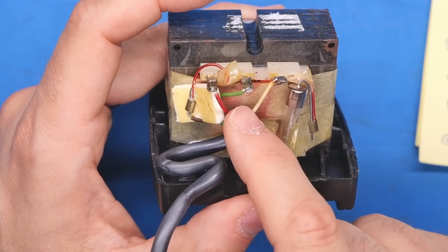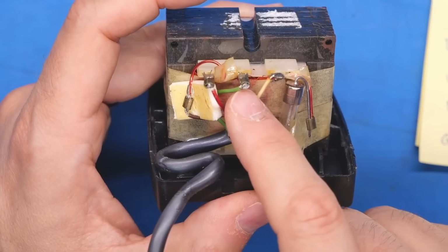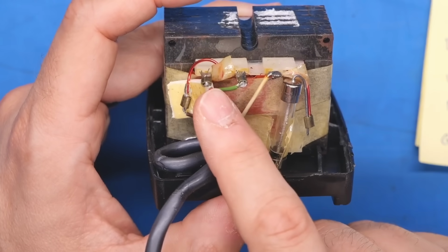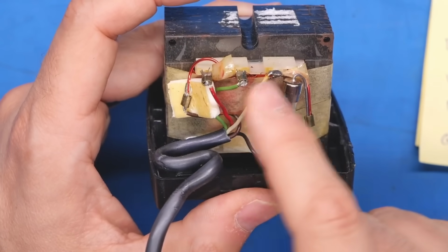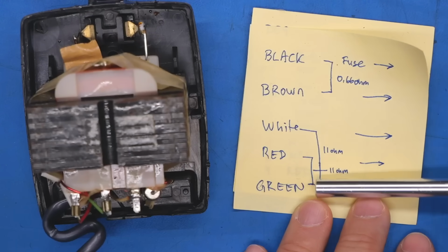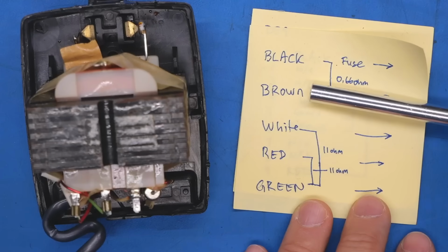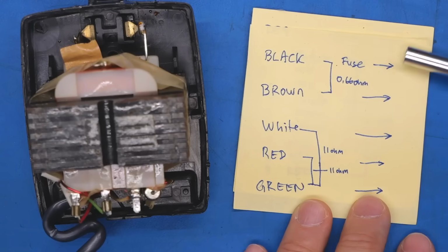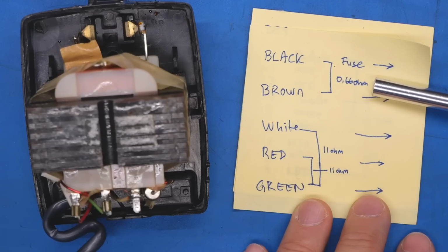And then we have these 3 wires on these tabs, which makes me think that the green wire is center tapped, with the red and the white wire providing a negative voltage AC and a positive voltage AC, or if you go between the red and the white, you would have double the voltage. So I documented what I see inside the brick, with the black and the brown wire being the 12 volt DC rail gets converted into DC and then regulated all the way down to 5 volts. And that's where we have the fuse. If you measure the resistance on that winding, you're getting 0.66 ohms, which shows it's relatively heavy duty.